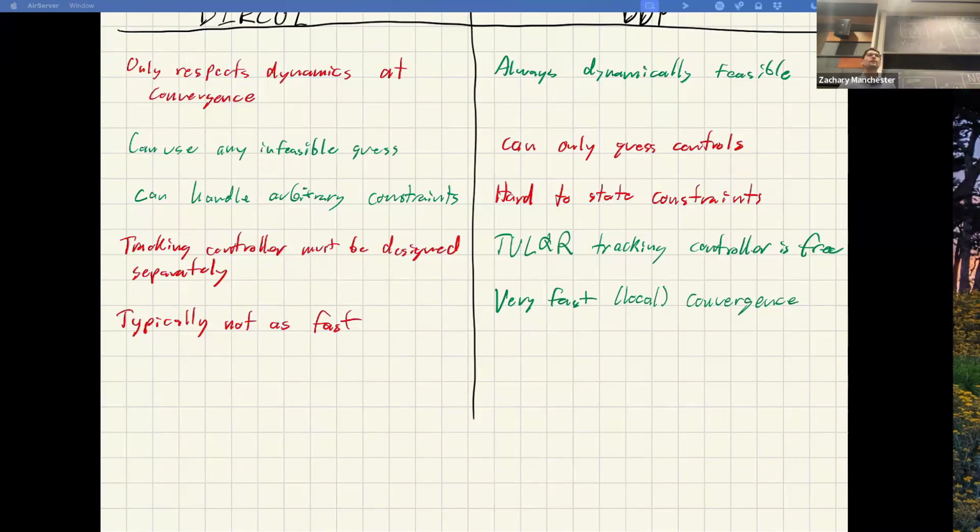It's designed to try to get you a solution to a hard problem that you hand it. And it has a lot of safeguarding and checking, that is, again, all for robustness rather than speed. Whereas with DDP, usually there are very few guardrails, and you just let it rip. And you can tune that offline and Monte Carlo it so you're pretty sure it's going to work. And then basically get rid of all the guardrails for the online version so it's as fast as possible. That's kind of what you would do.